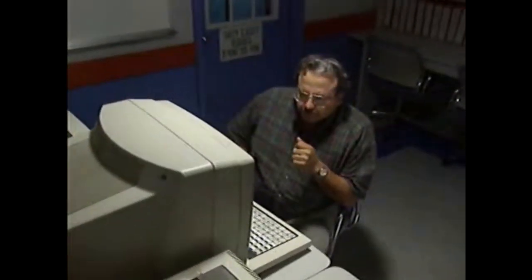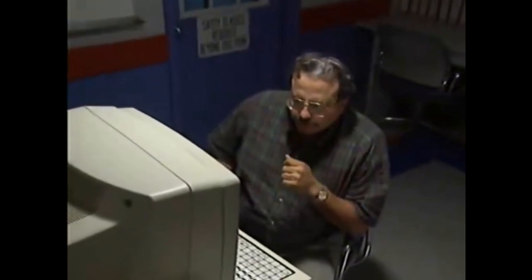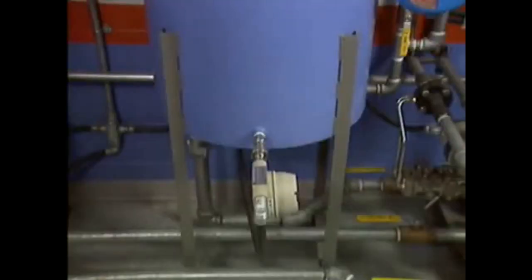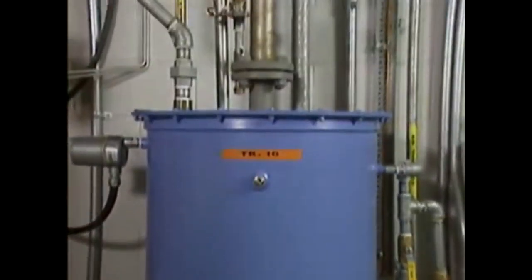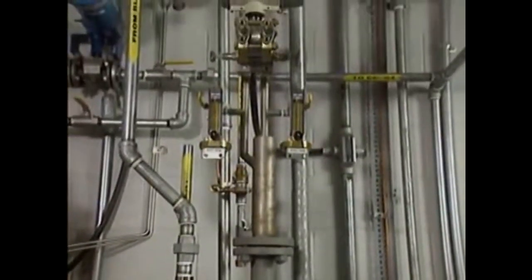The operators start to use the process of elimination to determine the cause of the problem. The control room operator decides to use the bracketing method to narrow down the possible causes of the problem. He starts by bracketing the system into 3 parts: the feed tank, the pump, and the collecting tank. The control room operator has the outside operator check the feed tank's level indication system for proper operation.